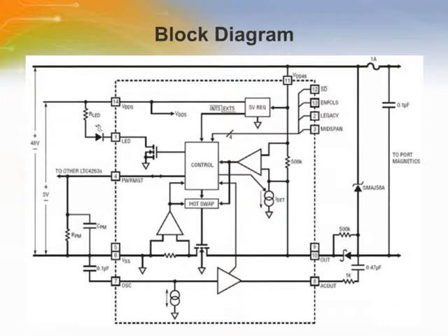Programmable onboard power management circuitry permits multiple LTC4263s to allocate and share power in multi-port systems, allowing maximum utilization of the 48-volt power supply. Built-in foldback and thermal protection provide comprehensive fault protection.